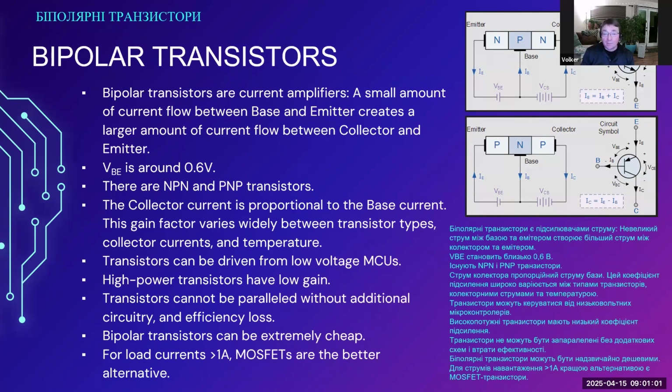So even, for example, if you have a very low power circuit that is running off a coin cell, let's say like a CR2032 3-volt coin cell, many microcontrollers can go as low as 1.8 volts in their supply voltage. The digital logic that we have just discussed, the HCMOS logic, for example, can go as low as 2 volts in supply voltage.